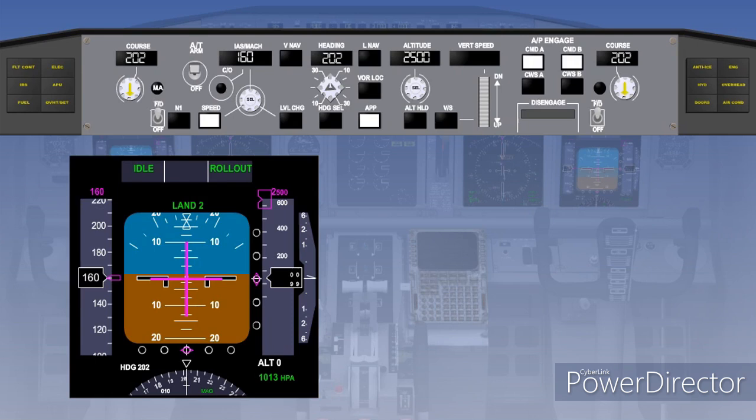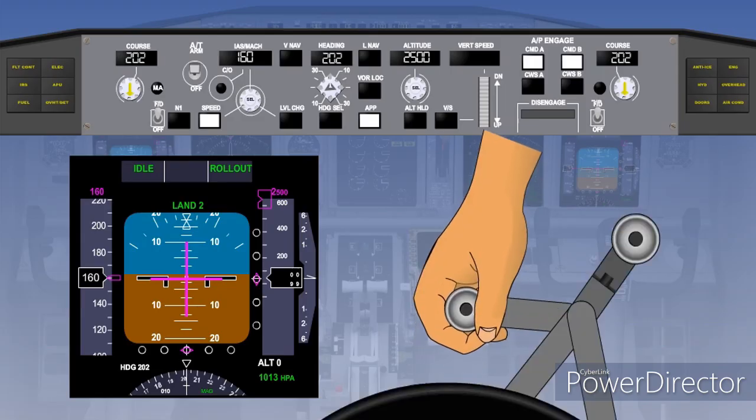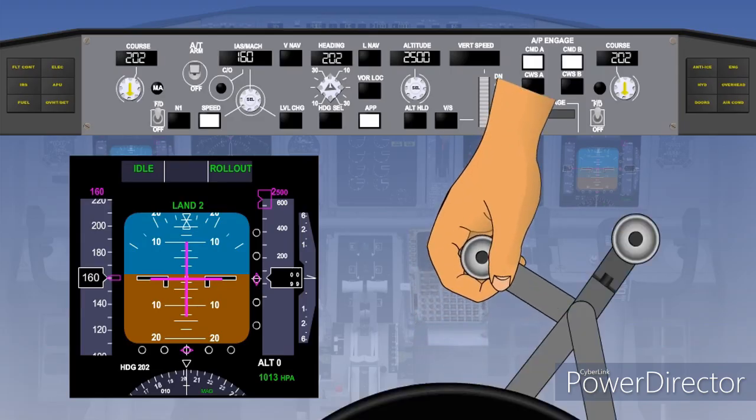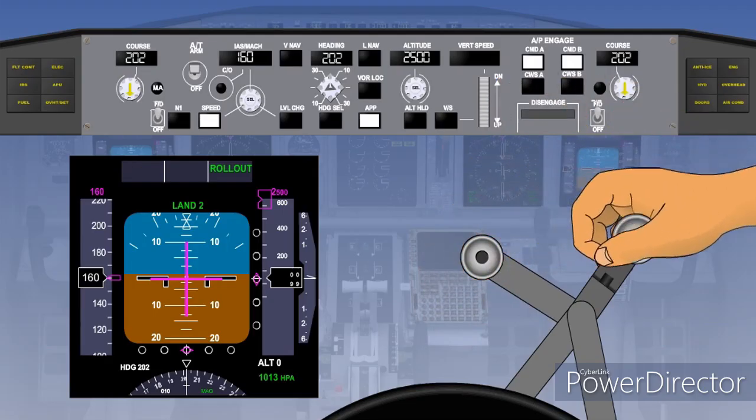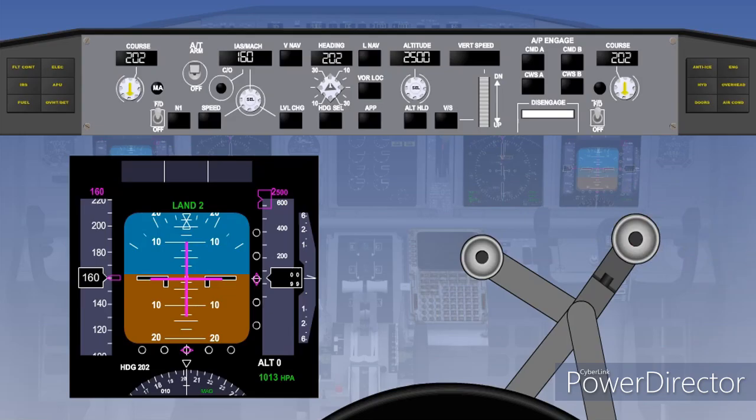The aeroplane then transitions into the touchdown and rollout mode, which causes the nose to be lowered and the speed brakes and auto brake to be applied if selected. When reverse thrust is applied by the crew, the autothrottles disengage. If the aircraft does not have rollout control or guidance as part of the autoland system, the autopilot will be disengaged at this point, and the rollout controlled manually.